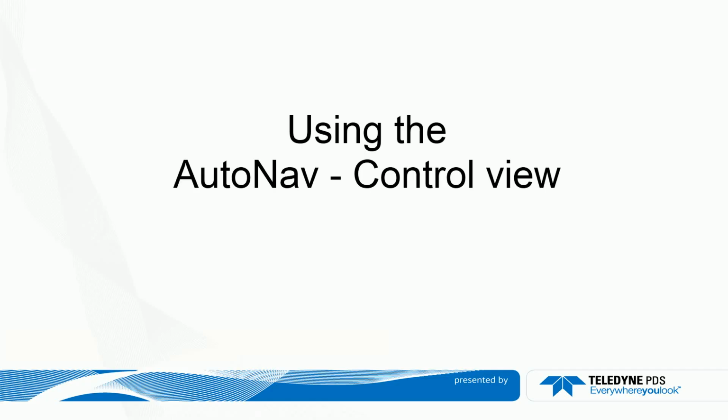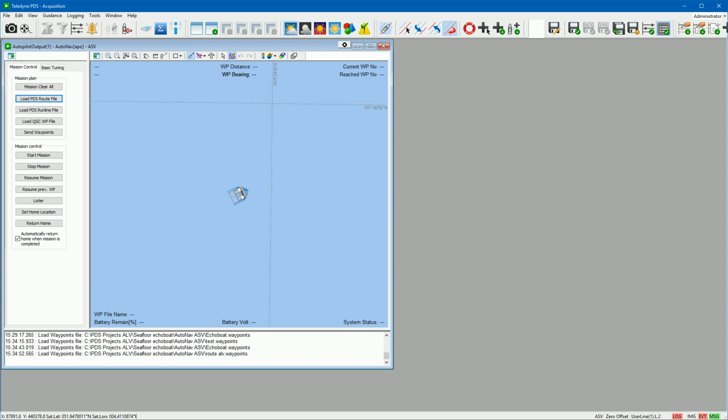Using the AutoNav control view. Let's have a look at how to use the PDS AutoNav control view. From the Mission Plan buttons we can load our line plan, run lines, routes or waypoints. To start or stop the mission of the ASV, or other mission options, use the Mission Control buttons. A route or a line file is created in the PDS Guidance Editor.